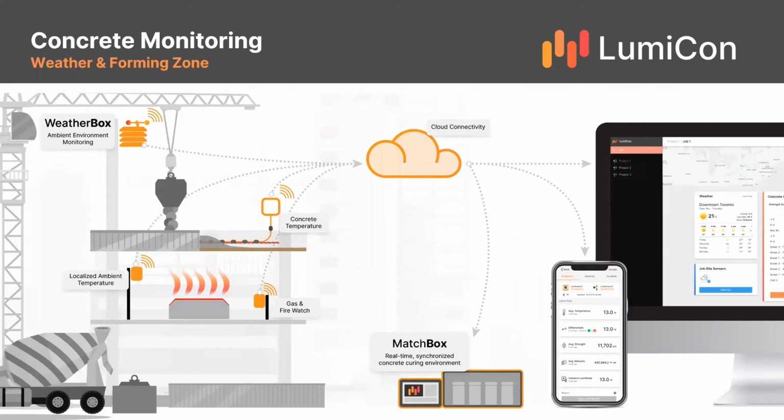It is the product that simulates the same temperature environment of your concrete inside the cure box. So basically the cylinders are going to be exposed to similar temperature conditions, to ensure the curing of those cylinders is close to the curing of the mass concrete. And we understand that there's an ASTM standard that requires curing of the cylinders at 23, 25 degrees C. This is obviously very important.